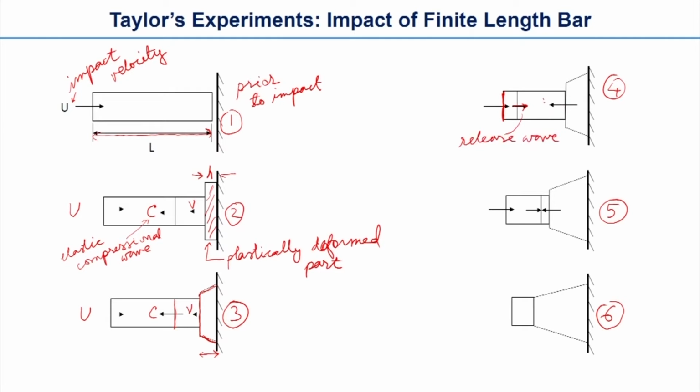Here the plastic wave is still advancing, and at some point this reflected elastic wave, the release wave, will meet the plastic wave.